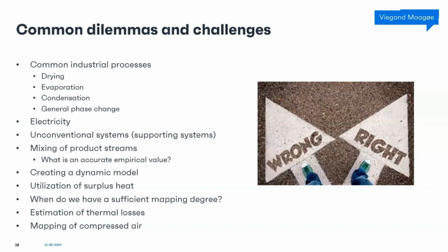We have talked about the thermal losses. It's very hard to quantify. You could come up with a figure by experience, or you could make some calculation. Let's say you have a system that you estimate consists of that many meters of pipes. You can make a calculation for 1 meter, a pipe equivalent, and then scale it up. Then you get the magnitude. So you can justify how you reached 3.5%: this is the approach because I don't have any better intelligence, so I've used this approach.